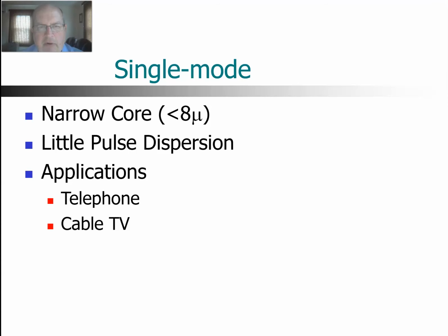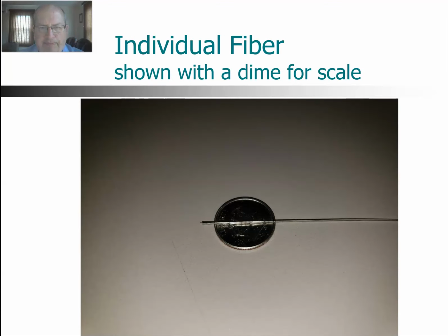You use a very, very narrow core and only one path for the light to travel, and therefore there's very little dispersion in the cable.